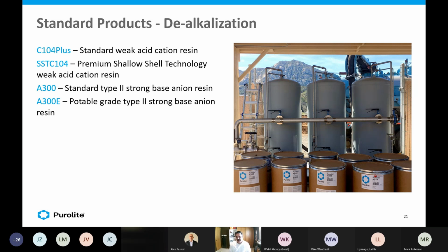Those are what we call a chloride dealkalizer, so it would basically just use salt to regenerate, much like a softener, but because it's an anion resin, the chloride would load onto the bead and it would exchange your alkalinity for chlorides. It would work exactly the same way as a softener, just in anion form, removing your alkalinity.